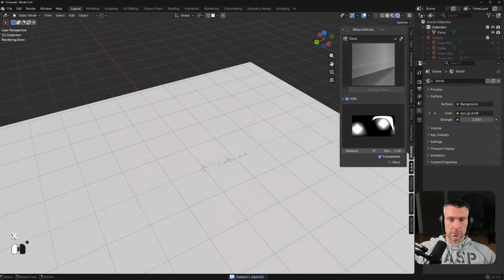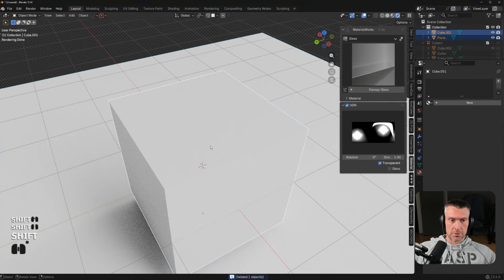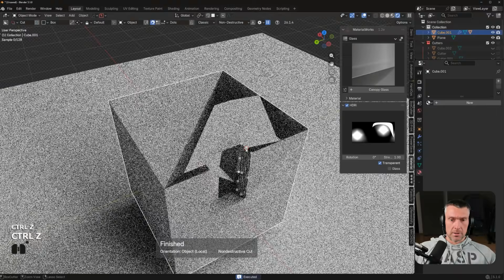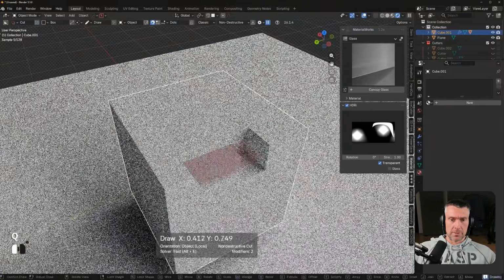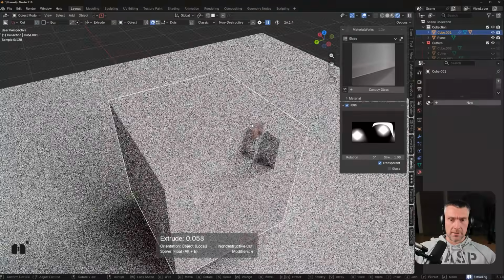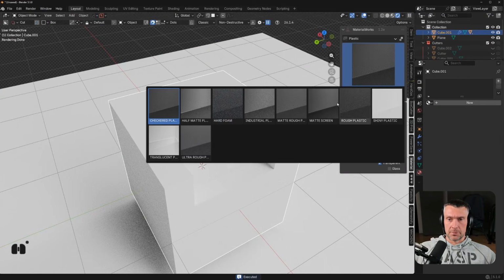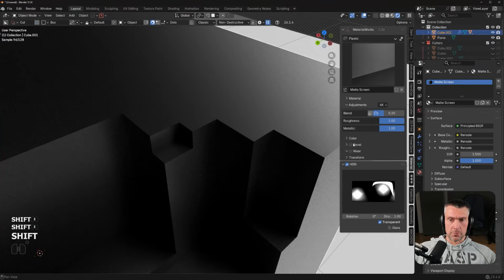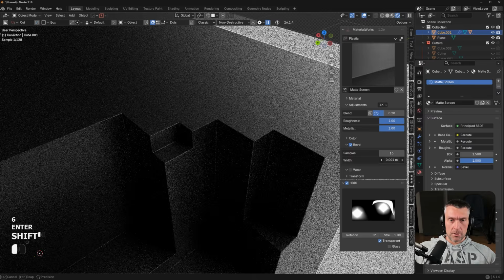For example, what you can also do with this add-on is not worry about bevels. Let's say you have a really complicated situation here in terms of cuts. There's a lot of cuts, and these cuts are kind of dodgy, and you don't really want to run a bevel on this mesh, because bevel is going to mess everything up. Let's say you've got really tiny cuts like this. No problem. Let's just pop some plastic, whatever, and you can actually run a procedural bevel with our add-ons. So you can just go here, turn the bevel on, change it to 16 samples, make it a little bit smaller with Shift, and look at this.